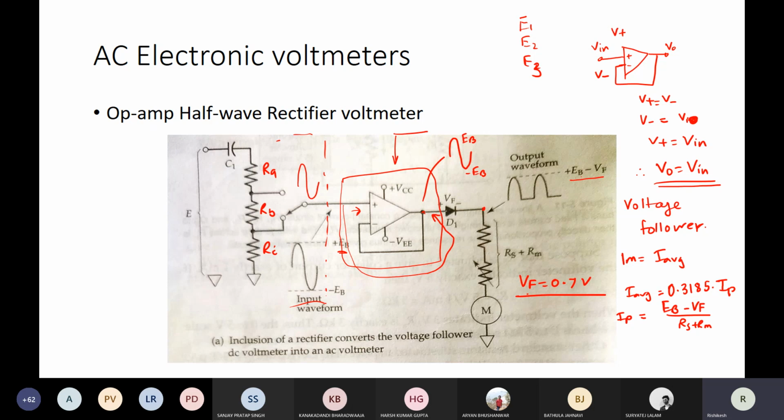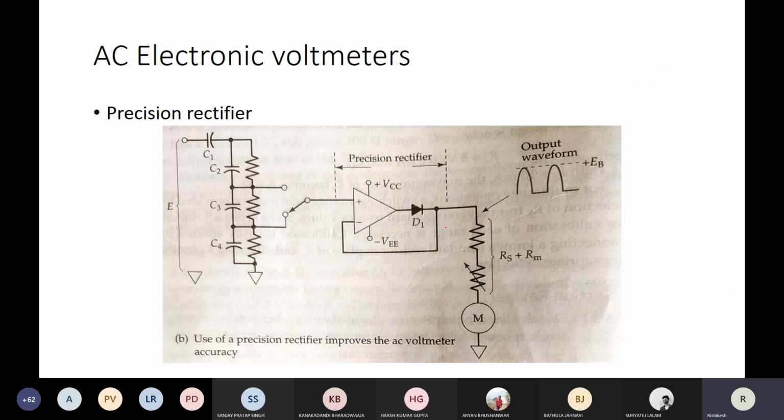If you remember in the transistor based circuit, the differential amplifier which we used for the voltage measurement, there we got rid of this 0.7, no, in case of transistor. How did we get rid of that? So one NPN and one PNP. No. They both were NPN that time. But we used another transistor to provide that reference of 0.7 volt, right? Yes sir. Here even that is not needed. Why? Because that extra drop can be taken care of.